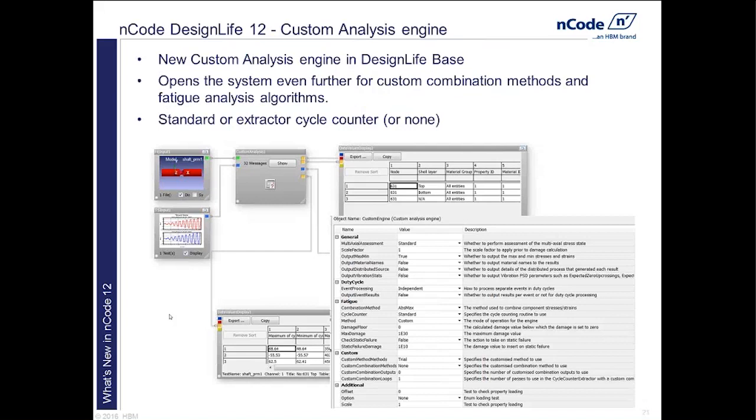We've also, as I mentioned earlier, expanded the custom capability within the product. Currently, we have custom capability built within the SN engine to do your own damage models and read your own material data in. And also, within the spot weld tool, we have a custom spot weld analysis, so you can do your stress resolution from forces to stress for spot welds specifically.